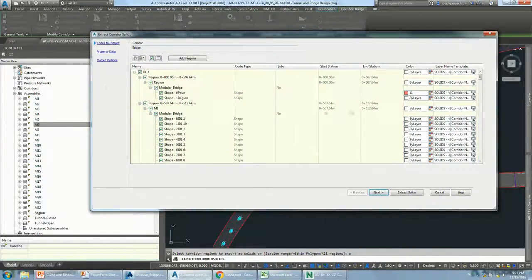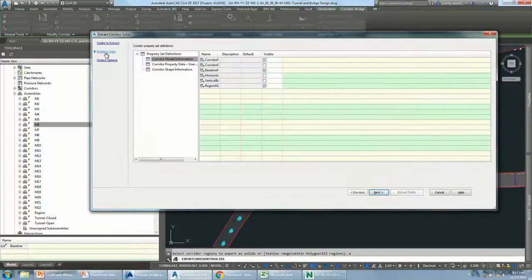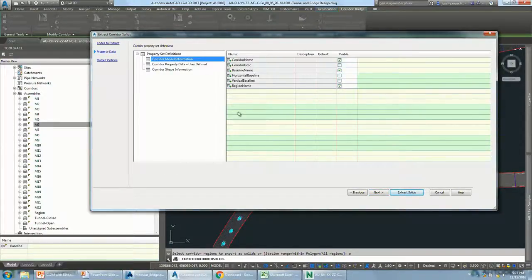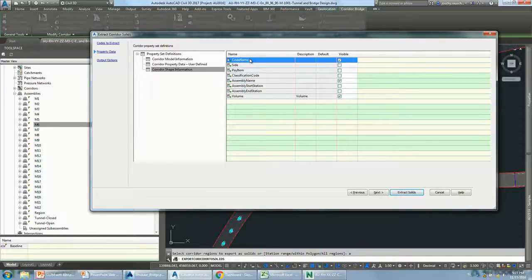And then it looks the same as always, but in our property data we can choose what we want to do. So here we will say, okay, I want my code name, because my code name is the ID for my sensor. This code name we are going to link in Navisworks, so we can see where the ID is and where the ID in our database is set.